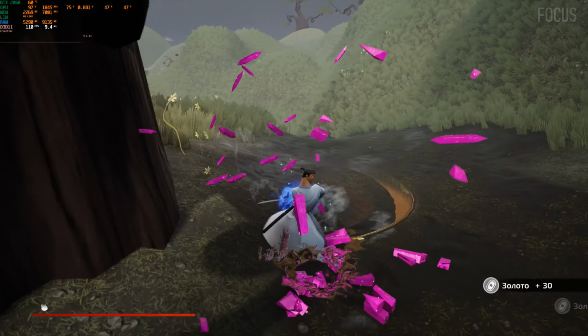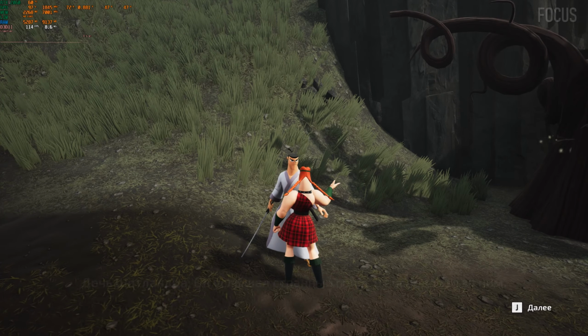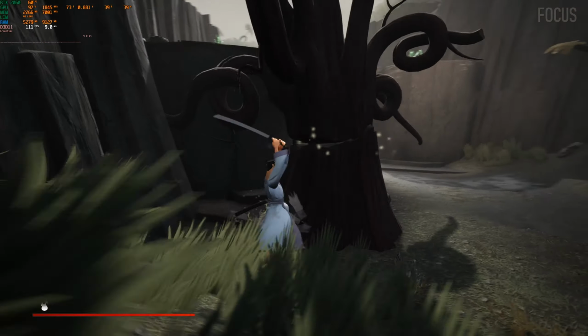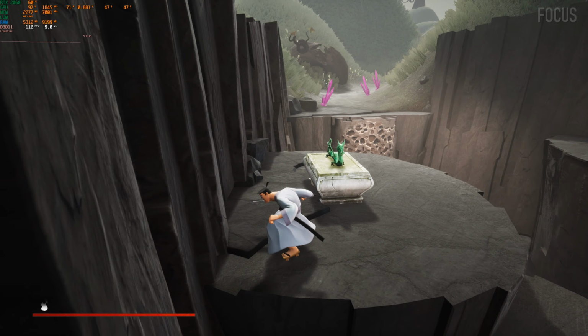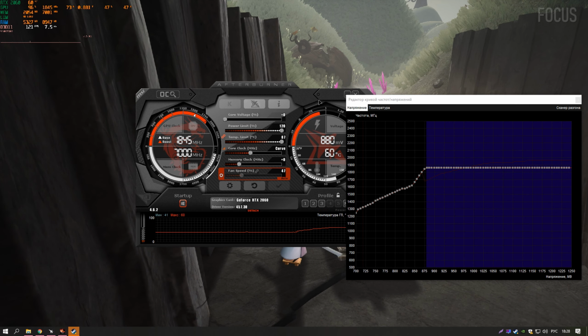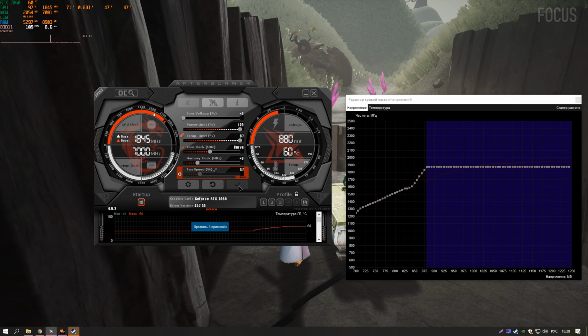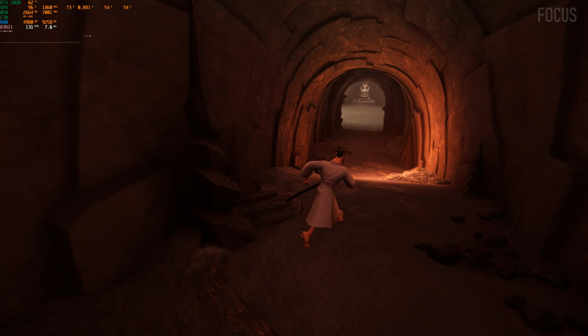Also, after receiving the first load on the video card from a game or program, I advise you to open MSI Afterburner and make sure that everything works as you set it. As I said, the frequency changes with the temperature of the video card. Most likely, instead of 1860 MHz, you can have, for example, 1845 MHz. We do the above actions.